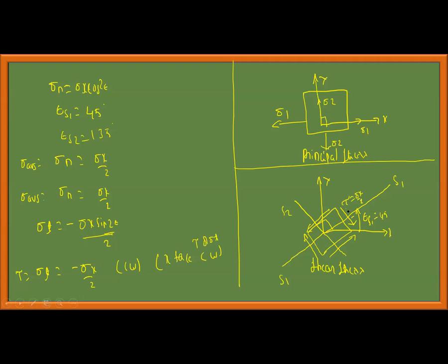What I have written is that I have found the planes where the principal stresses are maximum, 0 and 90 degrees. I have represented that on plane G. If you take this as plane G, this is a rectangular box. Now, on which planes are the shear stresses maximum? The S1 plane is at 45 degrees, and S2 is 90 degrees to that. I have written that plane. Now, how to indicate it? It is indicated by its normal. The S1 plane is at an angle of 45 degrees.